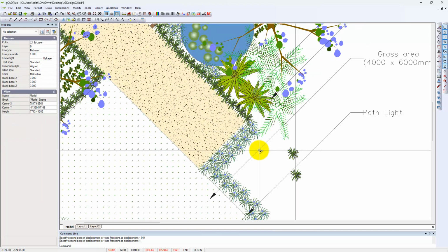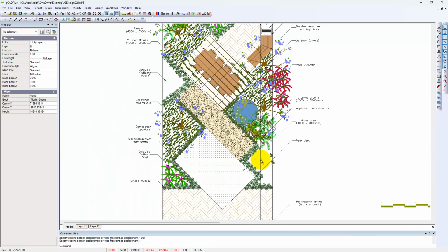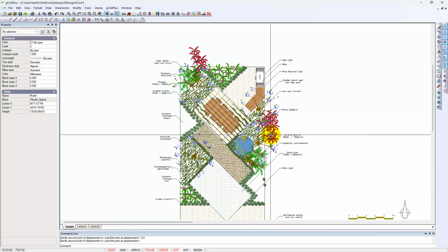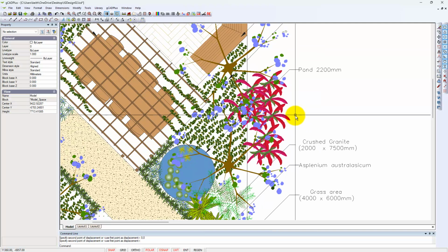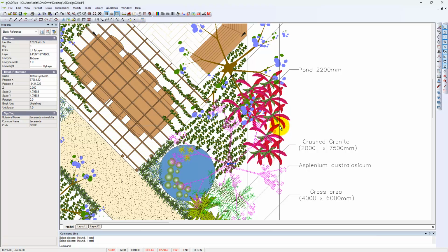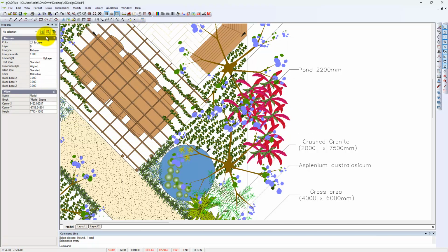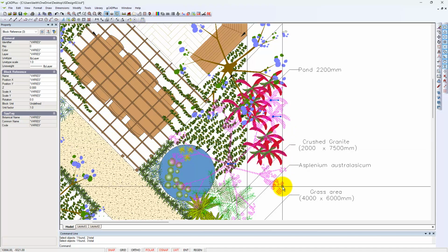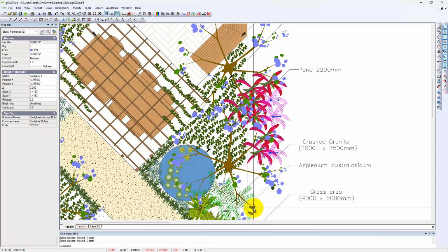And now the symbols appear to have disappeared. They have to be here somewhere, and we need to find them. And there they are. Because the base point has changed, I'll see if I can grab hold of them and just move them where they were. And notice that I can only pick one at a time, so I need to change that to a plus, holding the shift key down as I've inadvertently selected that one. Whoops, same again. So this is a little bit fiddly.